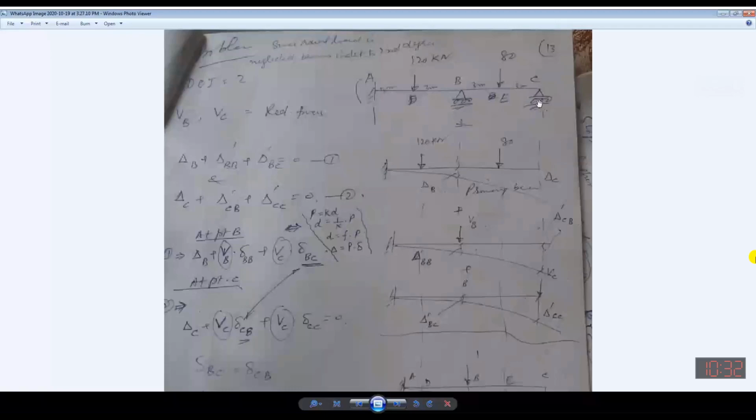Now the extra equations which are required are 2 in number. In the previously shared solved examples, you might have seen that only one equation was developed, and in that case you easily calculated and solved the numerical. But over here the degree of indeterminacy is 2, so you need 2 equations. How can those be developed?